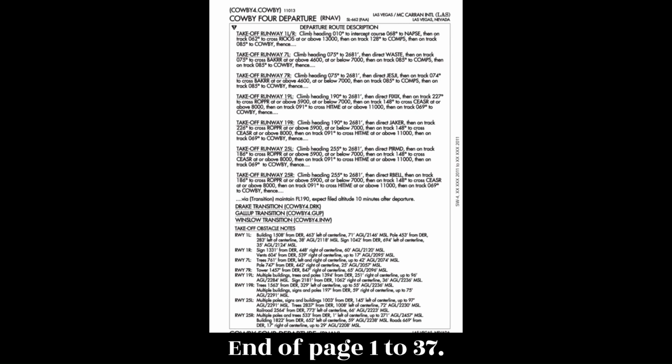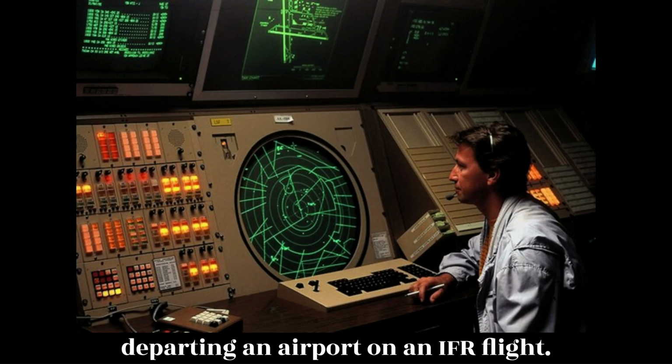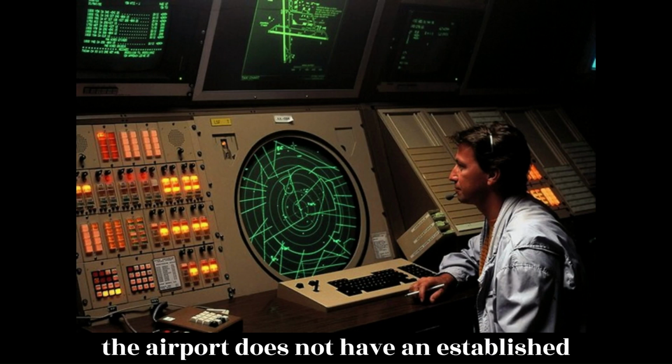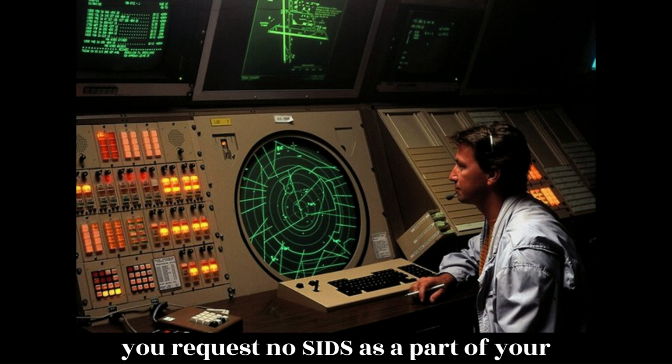End of page 1-37. Radar departures. A radar departure is another option for departing an airport on an IFR flight. You might receive a radar departure if the airport does not have an established departure procedure, if you are unable to comply with a departure procedure, or if you request no SIDs as a part of your flight plan.